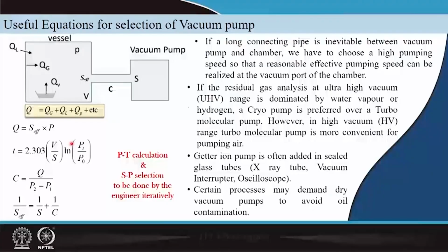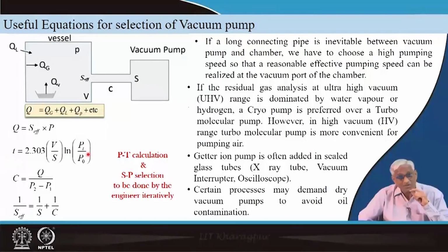Instead of 10 minutes, let it take half an hour. Once it comes, afterwards it is a load that is being pulled by the vacuum, equilibrium pressure, that runs for days together. So, how does it matter? Initially 1 hour takes 2 hours. So, this equation is very important in the semiconductor industry, particularly for load lock chambers, because if you can put the next chip, the next silicon wafer faster, you will get faster chip production.